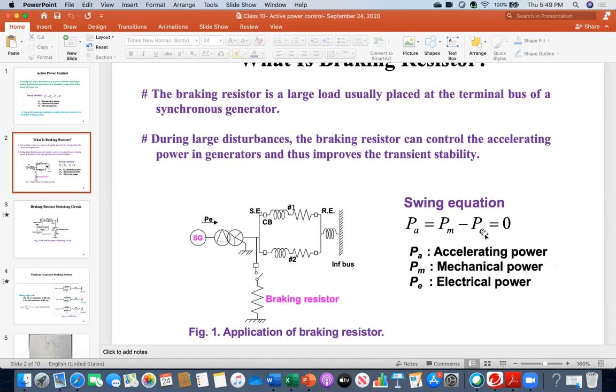But a fault may not always be a three-phase to ground fault. It could be a single line to ground fault or a line to line fault. There is a severity or ranking of faults. When it is a single line to ground fault, two phases are fine and only one phase is unhealthy. Do you think the same amount of power is needed to be provided?